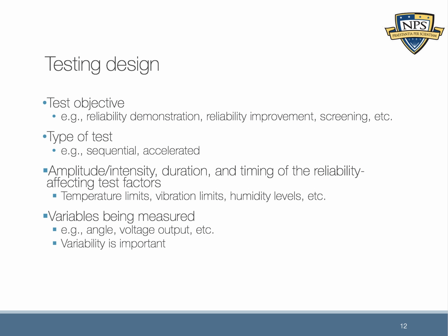And then during the ramp up, where they're heating up, you may turn them on again and sample them again. And then during the hot soak, you may do that again. And if one fails during the hot soak, the limitation is that you don't know at what temperature it failed. You know that at hot it's failed, but you don't know the exact temperature it failed at, because you may have tested it at hot soak, maybe 120 degrees Celsius. You may have last tested it at 55 Celsius. So all you know is that it failed between 55 and 120.